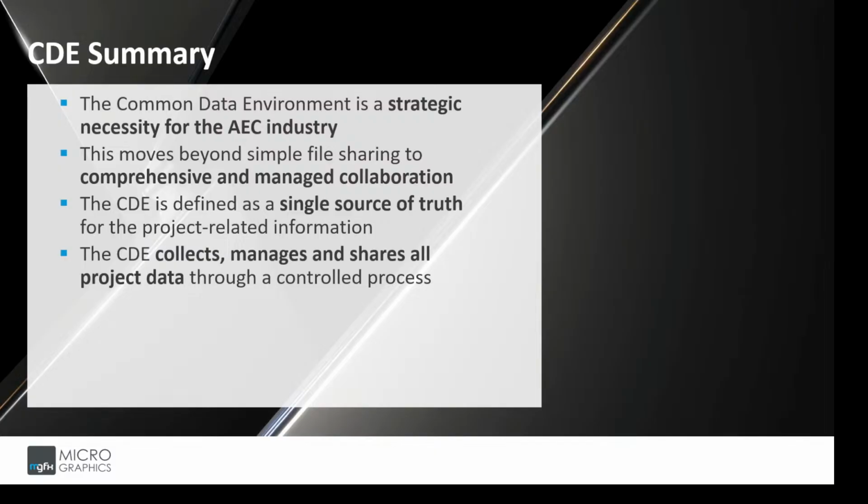The common data environment implements controlled information workflow. The CDE process, mandated by ISO 19650, governs how information moves through critical lifecycle stages: the work in progress stage, the shared stage, published, and archive. The structure, along with strict approval gateways, ensures that only authorized and quality-checked information is used for construction and design activities, providing traceability and security.